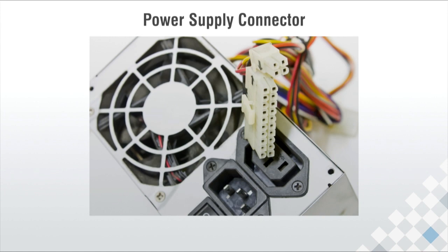If power quickly reappears on that wire, the system may attempt to come back on by itself, which causes the symptom of continual reboots. If it doesn't, then the system will just shut off. It's also possible that a bad power supply cannot provide enough voltage on this wire for the system to even boot at all. This results in the failure to power on symptom.